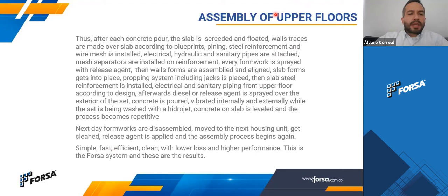There is another one here. It says, what is the resistance of the panels and how do you guarantee not to exceed it when pouring concrete? Okay, our aluminum formworks are designed for a strength of 60 megapascals. And if you don't want to damage your forms, you need to consider the speed of pouring.